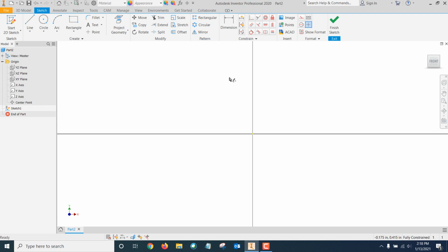It just makes sense. Now, once you start a sketch, keep an eye on your view cube and make sure that it's turned right side up. Sometimes when you start, especially with a metric template, or if you start drawing on one of the other planes, it may flip that box upside down. So you always want to check that.